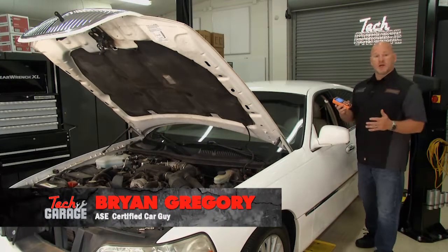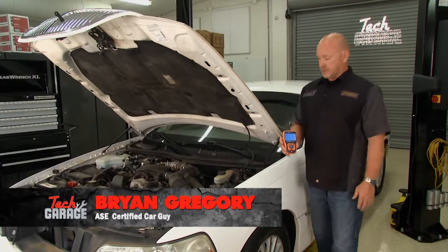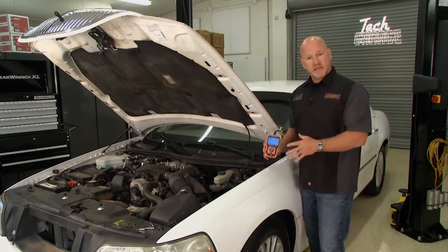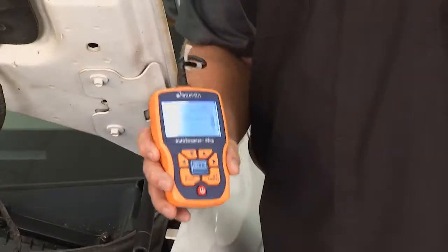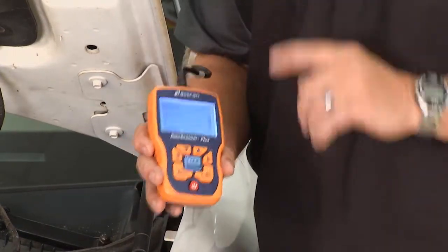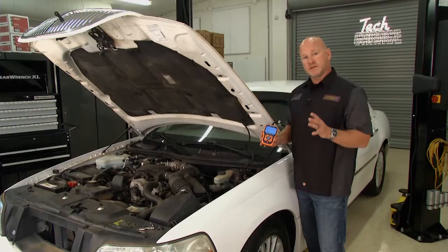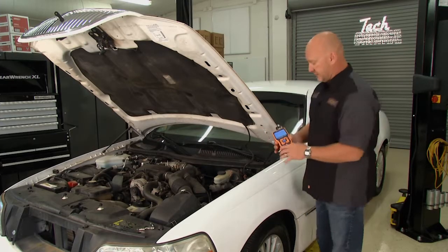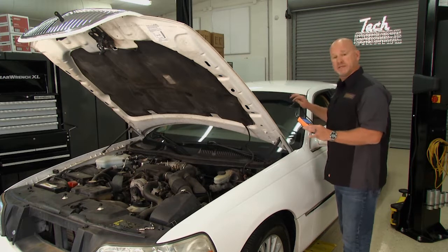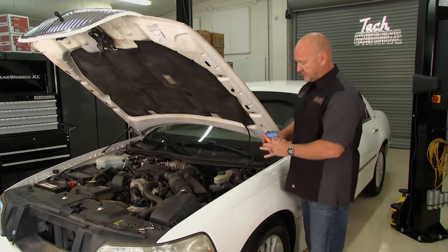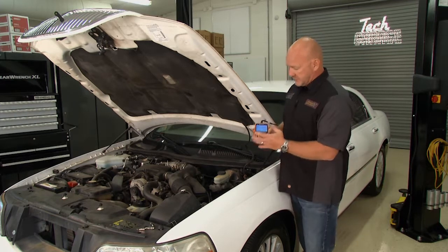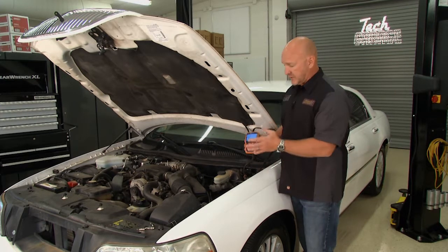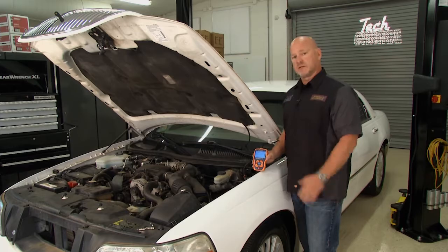Welcome back to Tech Garage, presented by Advance Auto Parts. Now, before the break, we told you we were going to scan the system to see if we'd retrieve any codes. We actually got 3, but the code of interest is a P0305. A small thing that means a lot if you're working by yourself: get a code reader that's got a long pigtail like this one, so you can be out here under the hood. Some of the more modern code readers actually have Bluetooth, so you can have your diagnostic screen up on your iPhone or your iPad and make this a little bit easier.